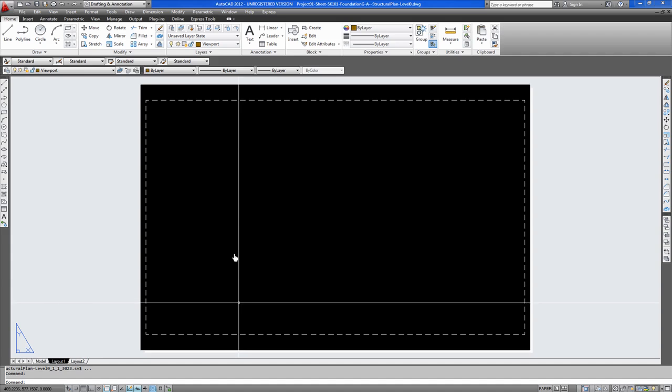You can use window. Now in this case, if I pretended that this line here, from one end to the other, is a drawing sheet, you would select, say, this endpoint and this endpoint of your drawing sheet. Ensure this is centered to plot, 1:1, this is unchecked, and preview. As you can see there, the drawing fits perfectly on an A3 sheet. You can press exit here or escape, and then OK to plot.